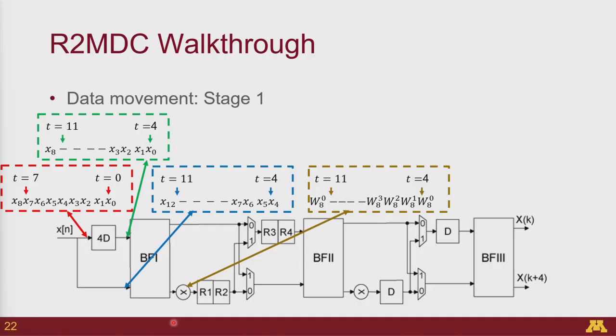Generally speaking, when you have control signals, you don't just directly pipeline the control, but you just change the control. So one way you could do it is to think of the twiddle as just coming from another block here, and then you put a pipeline on that path as well, right? But then you'd be unnecessarily creating registers when not needed. The easiest solution would be, instead of reading the 0th value, just read the first value, for example. So generally in control, we avoid explicitly designing the pipeline register, but we just move the values as needed.